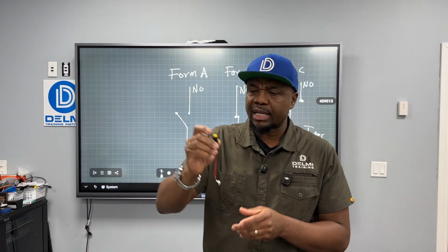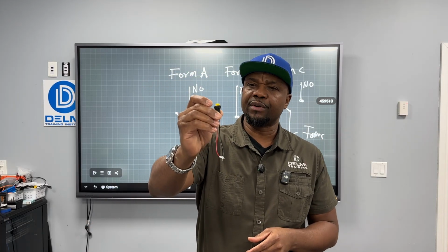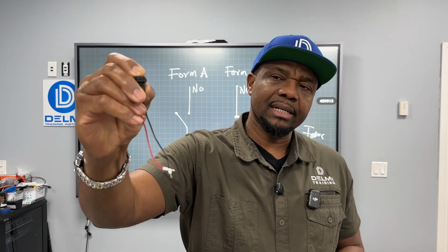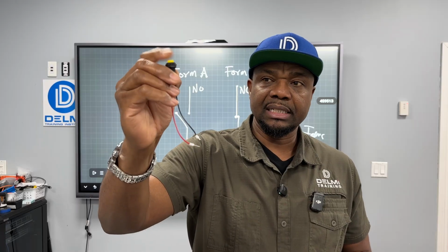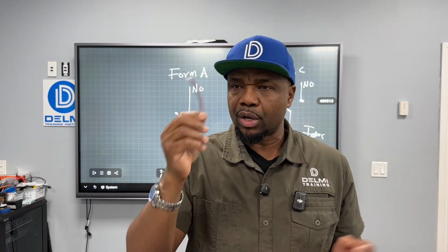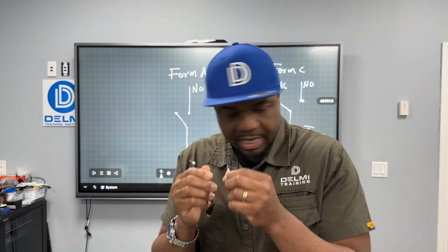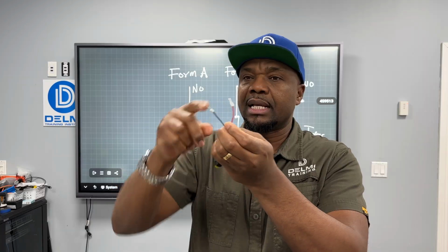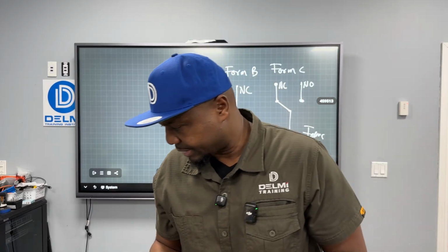We also were looking at some of them. Look at this one, for example. When I press and hold, it stays in. But when I take my finger off, it comes back up. So this is the default state. So this switch is called a momentary switch. That's just how I can tell. And for me to be able to tell whether it's in the open or the closed state, I need to take the digital multimeter, connect it to these, and then I would be able to test.